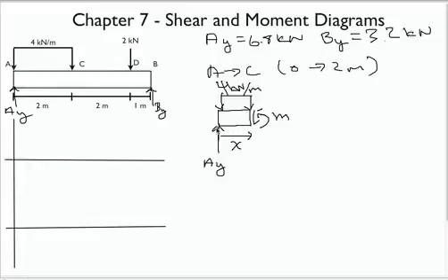And that is, if you are traveling through the beam from left to right, you orient the shear downward and the moment in the positive direction on the cut face. If I was going from right to left, I'd do it the opposite direction. So if I was going from right to left, here's BY, right? And then maybe we've gone far enough to include that one. Here we're going to have the shear pointing up and the moment being negative. Okay, so again, keep in mind the sign convention: when going from left to right, like you read a sentence, the shear is pointing down and the moment is positive. When going from right to left, the shear is pointing up and the moment is negative.